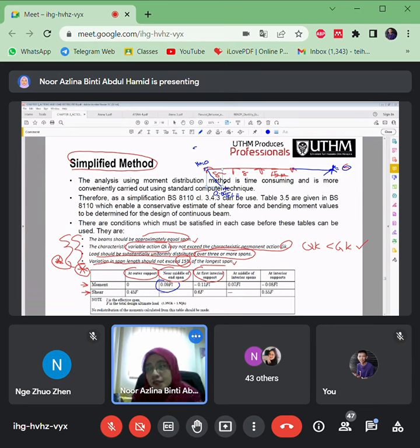Easy, right? At the first interior support. If earlier this was the outer support, then this should be the first support, where the moment is negative. Remember, we have positive and negative moment regions, right? So negative 0.11FL. Negative, of course, should be upward, right? So the moment here is negative 0.11FL. Just substitute the value in order to know the moment here.